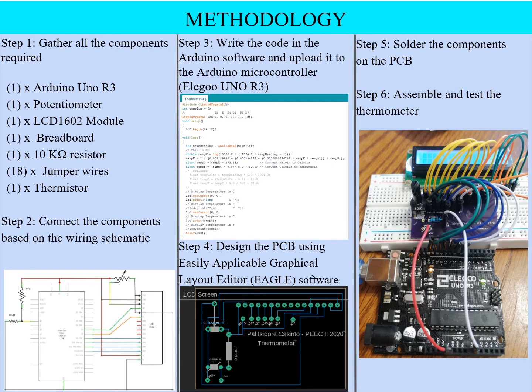Aloha, my name is Alika and I'll be covering the methodology portion for this segment. Our first step was to draft the circuit board, and we used the Eagle program to do so. We sent over the schematics after we were done to a mainland company called OSH Park for manufacturing. And while we were waiting for them to return our circuit boards to us, we drafted up cases for our microcontrollers using SolidWorks and later a 3D printer to print them at school.